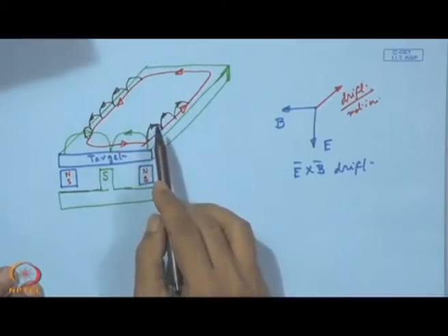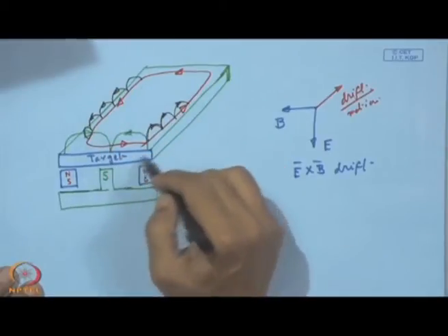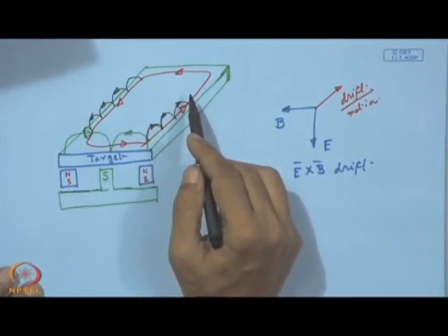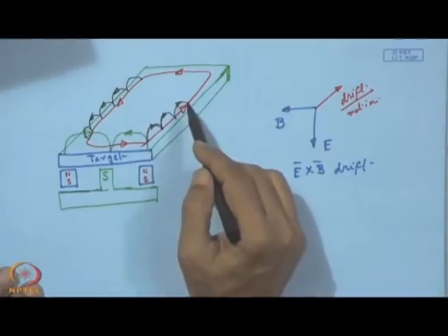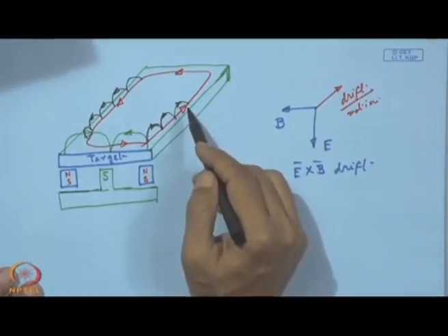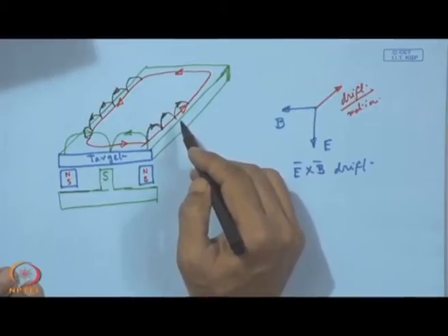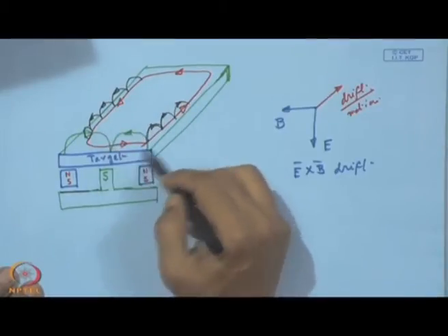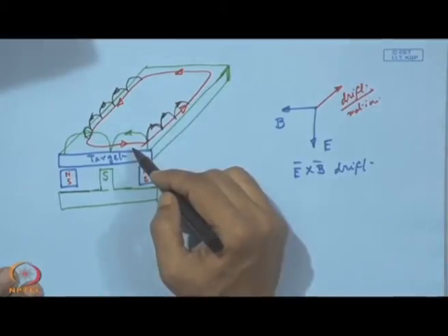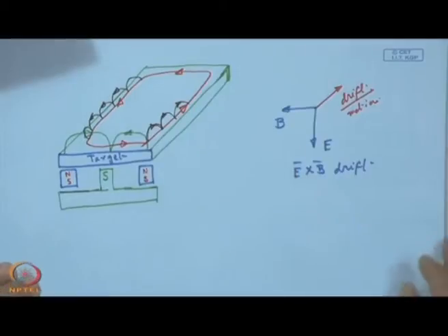So, this way one can consider the effectiveness of this magnetron and how it makes the secondary electron more and more efficient, in that it is now capable of splitting and ionizing more neutrals than ever before, when it was not trapped or locked by this magnetic field, where it had free access to move from the cathode surface to the anode surface.